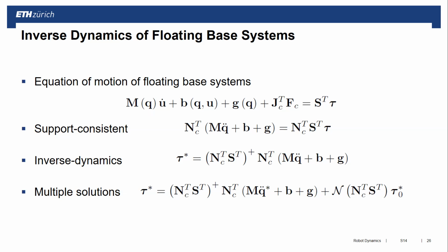So the torque is a function of my desired q double dot, which can be a PD rule on my q's, on my errors. And again, we have this pseudo inversion in here. What does that mean? If I have a pseudo inversion, there must be, or there might be, a null space to it. This pseudo inversion has a null space, which allows us to change the torque without changing the task of how I'm moving.